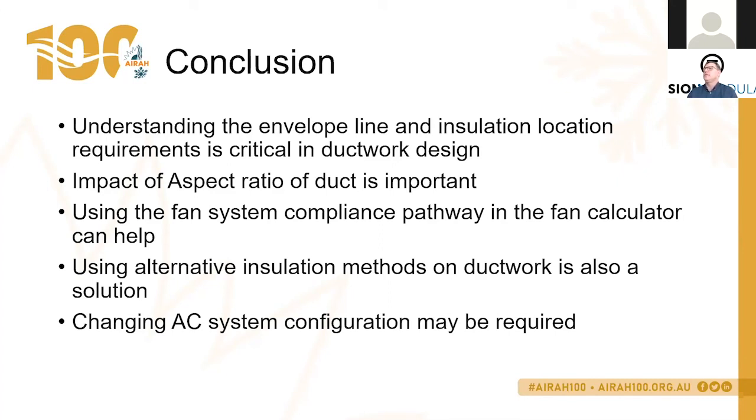So if it's process related, you just need to determine in your production facility, is the air conditioning specifically applied for the process, or is the air conditioning applied for the people in the room that are doing the production but not the process itself? Then the people in the room are the ones being provided with the air conditioning, and the air conditioning system still has to comply with the code requirements. So it's project specific really, and application of the HVAC equipment.